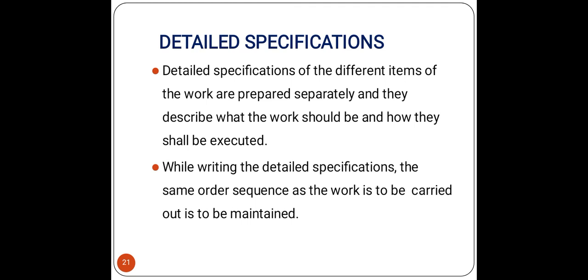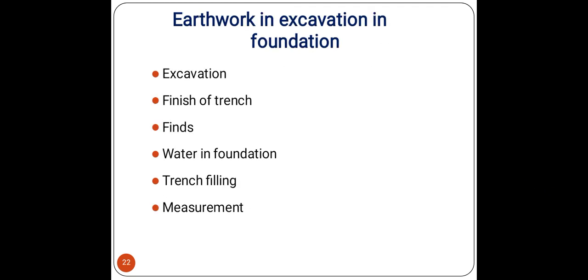Detailed specifications of different items of works are prepared separately and they describe what the work should be and how they shall be executed. Also, while writing the detailed specifications, the same order sequence of the work to be carried out is to be maintained. Now, what all things are included in the detailed specification for earthwork excavation in foundation? It includes the excavation, finish of trenches, fines, water in foundation, trench filling, measurements, etc.